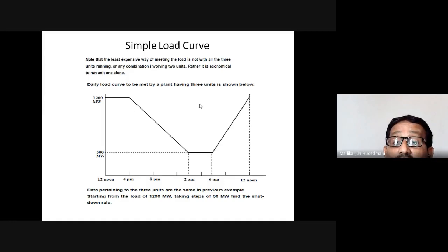Then, to understand this, it is not intelligent to target 1200 megawatt and keep all the generators on the entire day. For this kind of load pattern, I must decrease the production so that fuel burning and fuel usage are minimized and fuel is reserved for future use. In this way, intelligent choices must be taken. Therefore, it must be worked out carefully according to the load curve. This is how the load curves of each station in a generating area are very important.